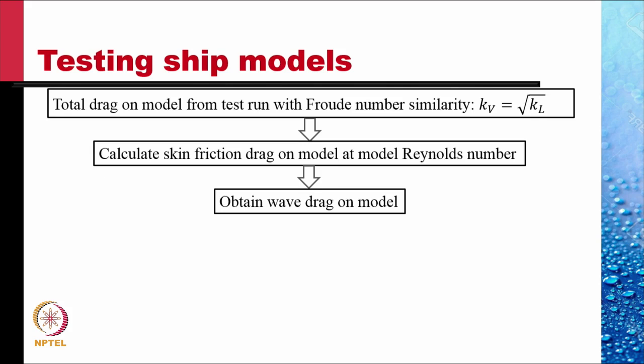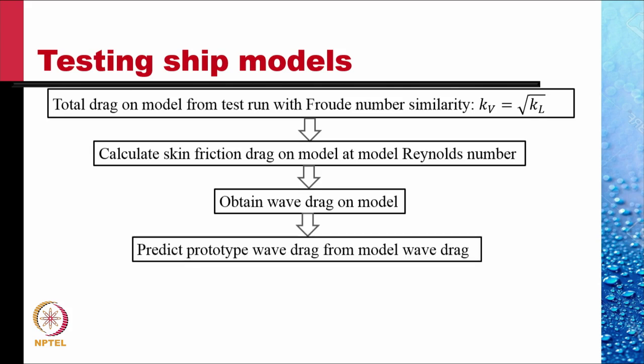The wave drag on the model must be scaled by using the Froude similarity. So predict the wave drag of the prototype from the model wave drag.